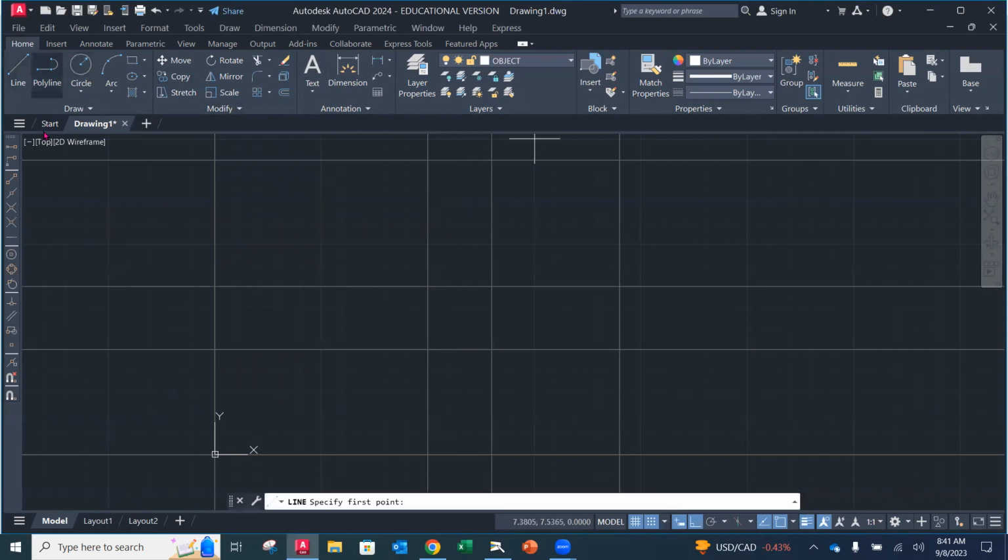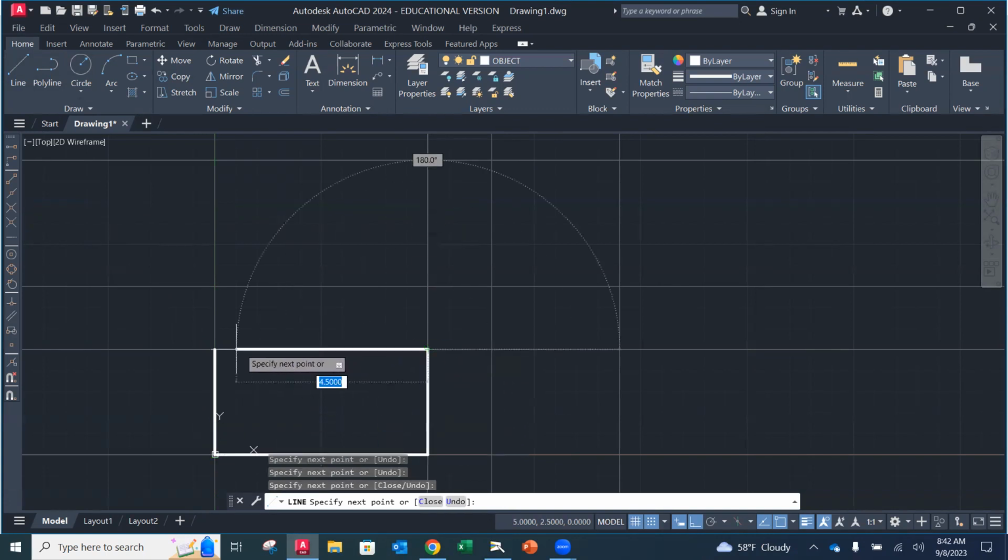So now I'm going to click the line command, and I'm still in Snap, and you'll notice that all of my increments are on the 1/2 inch increments. So I'm good. I'm going to continue to use that. So I'm going to snap. It's going to grab the intersection, and then I'm going to go straight down to that corner, over, making sure that I'm on the perimeter each time of each view.